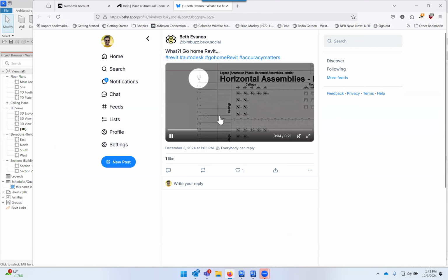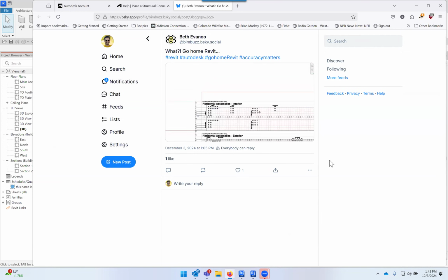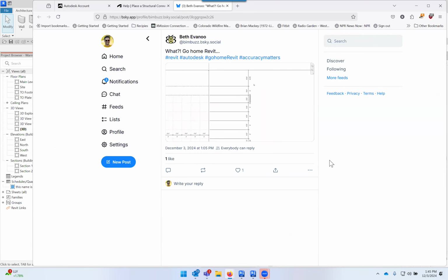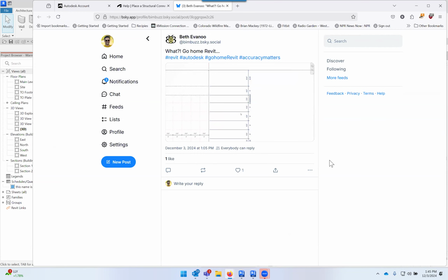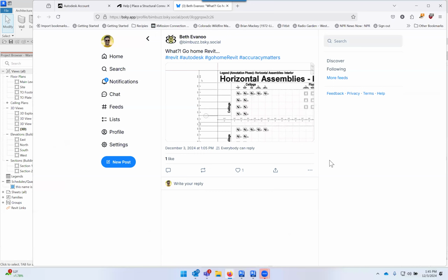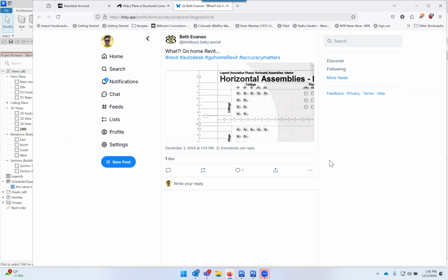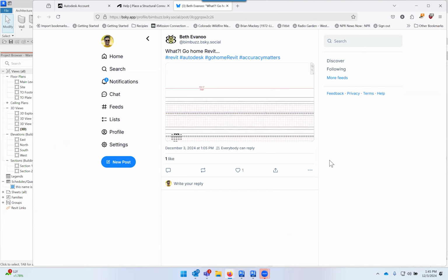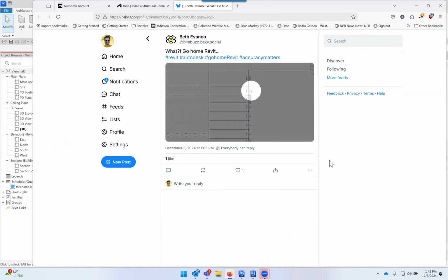Oh yes, the long lines and different dimensions where they're right on this side and wrong on the other. Oh yeah, I've had that. I have a project that's currently doing that. It's not even the fact that the line may not be straight. A client has a wall drawn and a grid drawn. On the first floor, there are 6-inch dimensions all the way around, going out 10 decimal places. When I get to the third floor, one side is 6 point blah blah blah, but the left side is still 6. Theoretically, that means one of the walls is not plumb or the grid is not plumb.